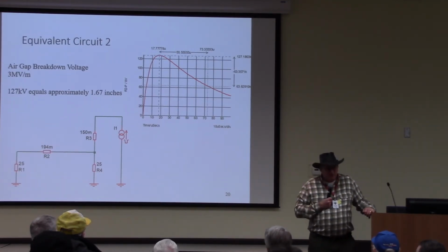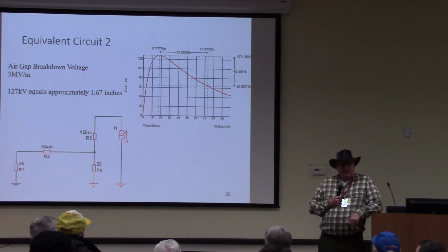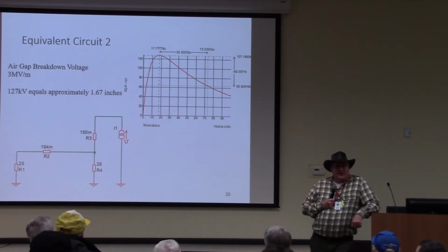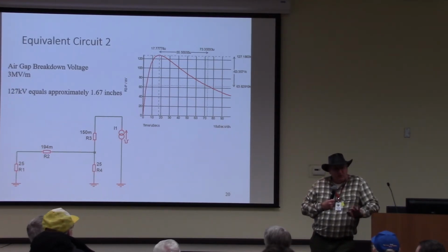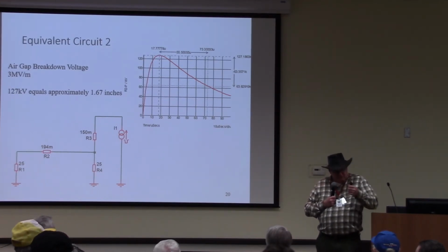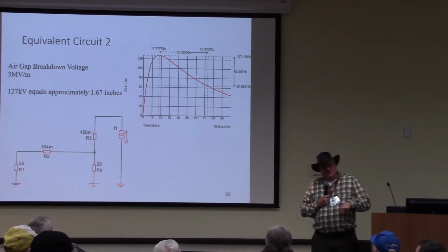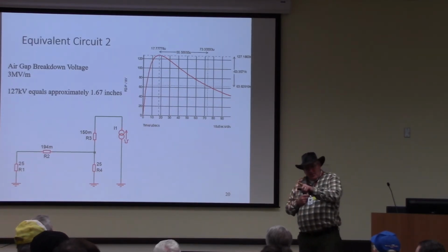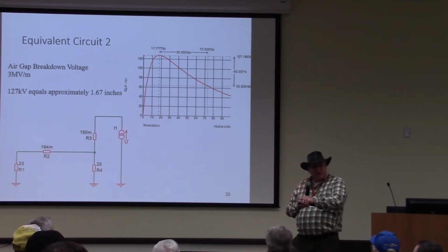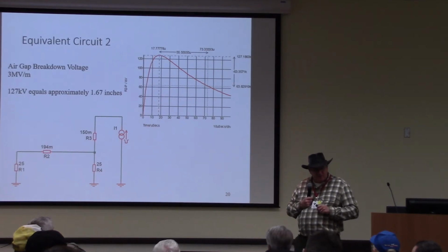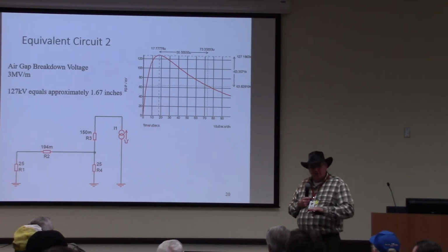Correct. So as far as melting and all, yes, it could probably handle it. It does handle it with no problem, 14 gauge wire. However, the voltage potential across it is going to be higher than if you use 6 gauge. Plus, he's got bare copper number 6 buried, so the surface area in his number 6 is going to be greater than the surface area in 14. So the impedance is going to be lower.